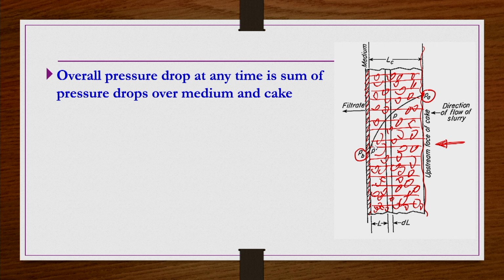What we can see here is that the pressure drop shows a non-linear behavior, because particles of different sizes will in general be there. When these particles are packed as a cake or bed of particles, the fluid coming through may keep changing the packing structure, and voids may keep changing from one layer of the cake to another.